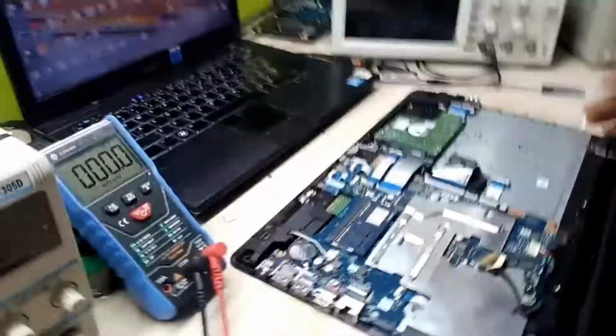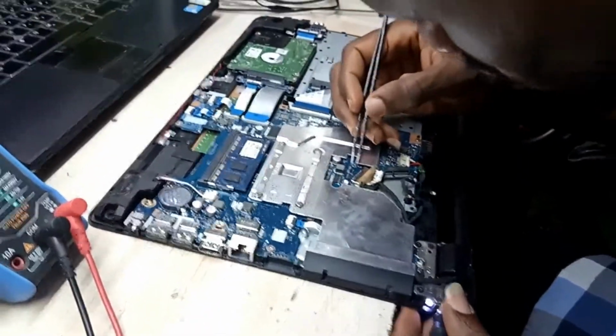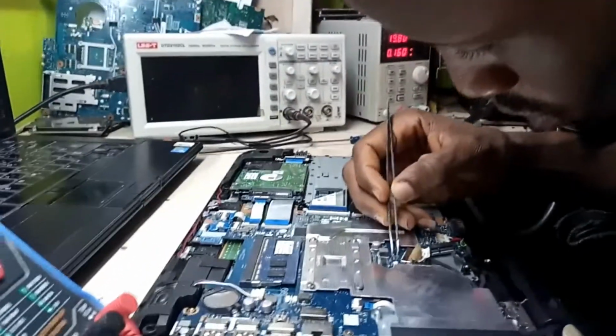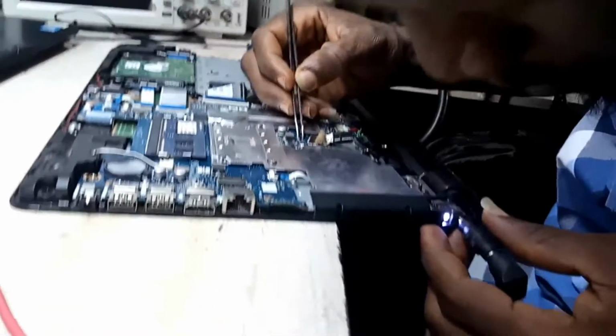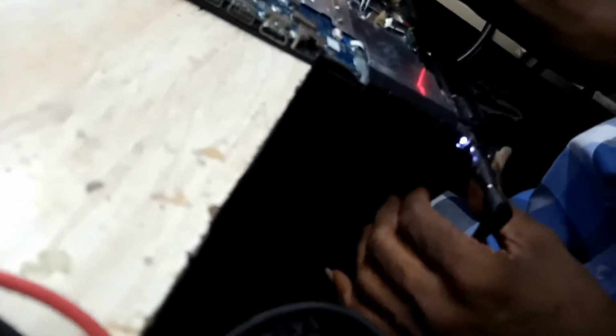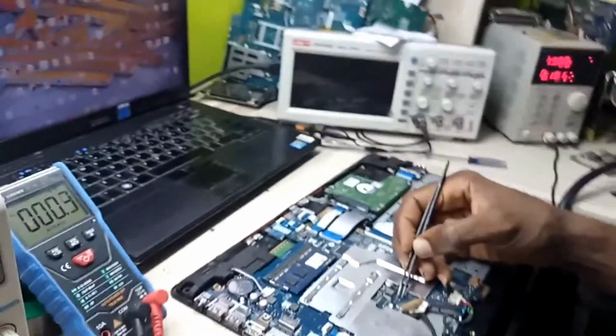This is my picker here. So if I jump input to output, I should have display here. Now I've jumped it and nothing is happening on the screen. Nothing is happening on the screen. Let me confirm if it is really jumping or the voltage is dropping after jumping.